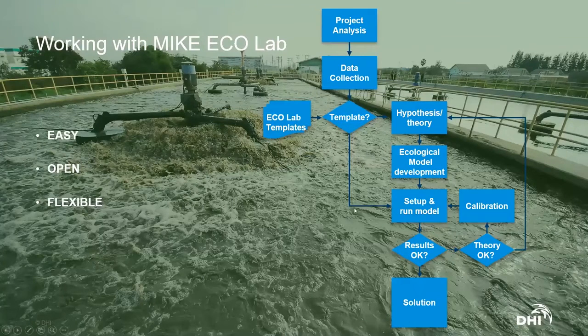And then you actually set up and run the model. And the setup is basically applying information on the bathymetries or the river network, the bed shear stress, and physical forcings like wind, solar radiation, or whatever. Input from tributaries or point sources or whatever.